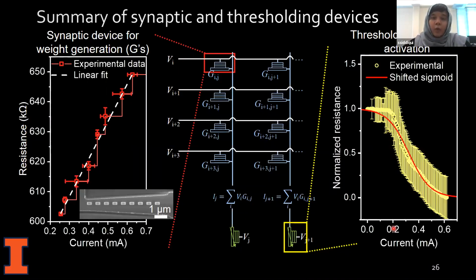In that case, I would believe if we go for the analog device, then we can remove that magnetic tunnel junction requirement. Now the domain wall stays in the same position, which is the main thing we want, because you want the non-volatility. Once you set the domain wall and you don't want to change the weight of your device, then you don't do anything. But for training, this is really one of the drawbacks of not only the spintronic device but any non-volatile device: it still needs some external switches and external CMOS circuitry, and you cannot operate without them. You get some advantages, but you still have to worry about the peripheral circuitry and also the data movement there. So I still don't see any way to get rid of all that peripheral circuitry and do all those operations just within the spintronic device.